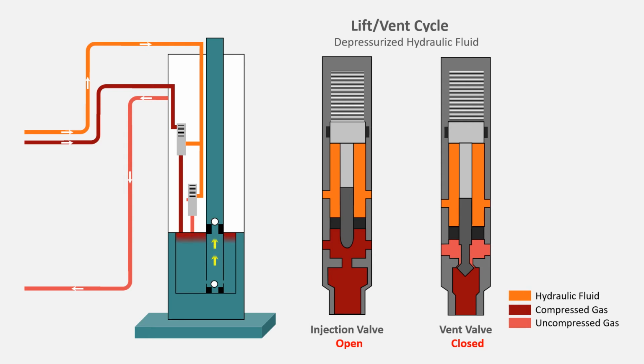The pressure causes the chamber entry standing valve to close, isolating the reservoir from exposure to high pressure. And as the injection gas pressure overcomes the hydrostatic pressure of the full column of tubular liquid on it, the tubing entry standing valve is pushed off its seat. The chamber's accumulated liquids are emptied and completely flushed into the tubing, and the chamber is ready to be filled again.